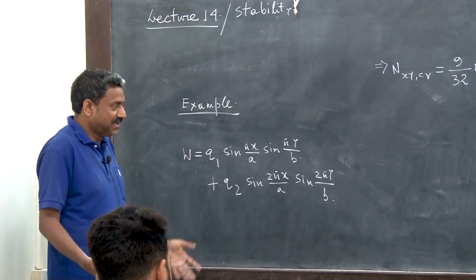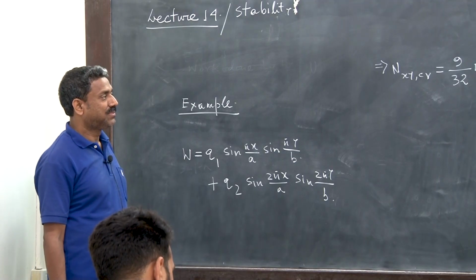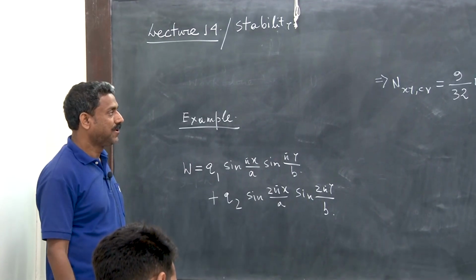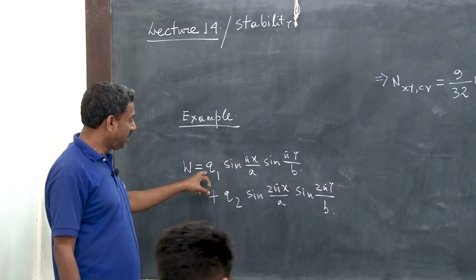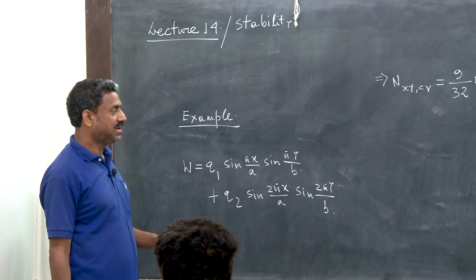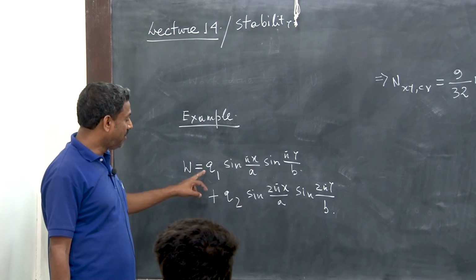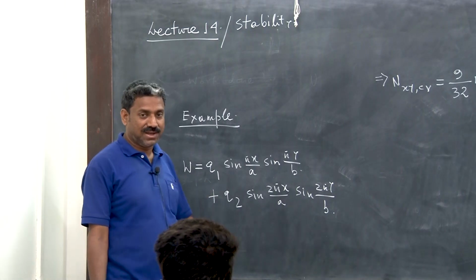You will get the first mode and second mode. Here also the first mode will be symmetric, and for the second mode, substitute and see what you get, because from the algebraic eigenvalue problem the eigenvector gives the relative values of q1 and q2. Maybe for the first eigenvector both will be positive, and for the second one will be positive and the other negative, so some asymmetry will be there in the second mode.